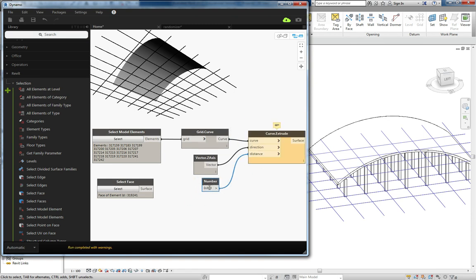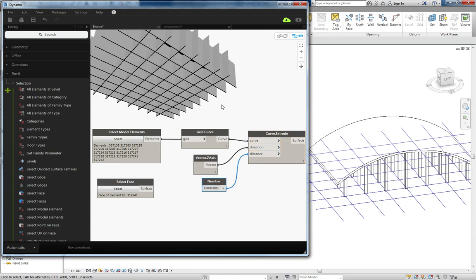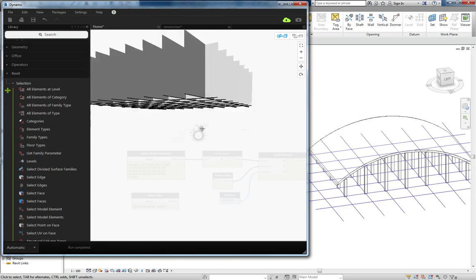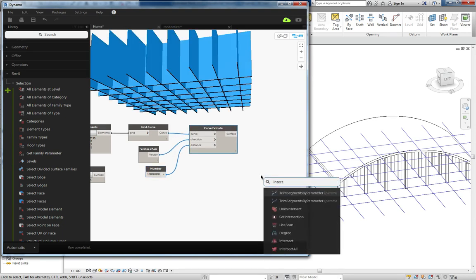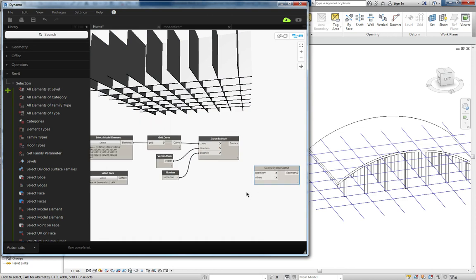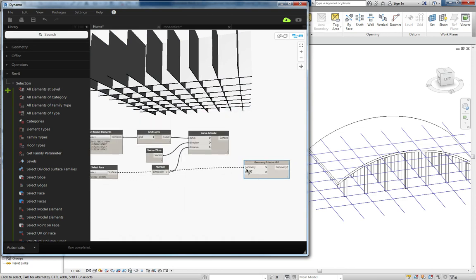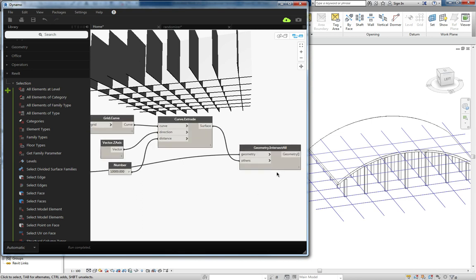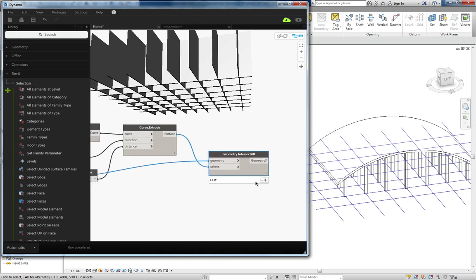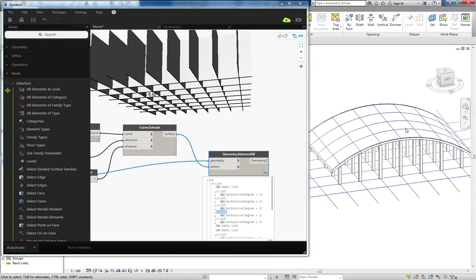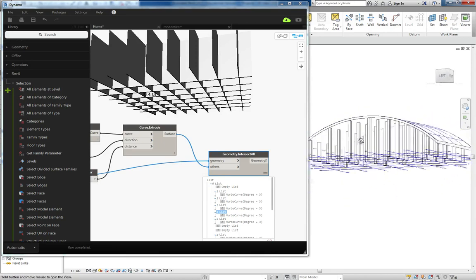In this case, I'm giving it 10,000 to make sure they're going through the whole roof. It looks like they are. And then I'm going to do the intersect all that we just used. So I'm going to use the surface that I had with these new surfaces that I drew. Got a list of emptiness. Okay, let's try this. So I would do placing, cross product. Alright, now you can see it has cut through the roof, all those beam lines that I wanted.